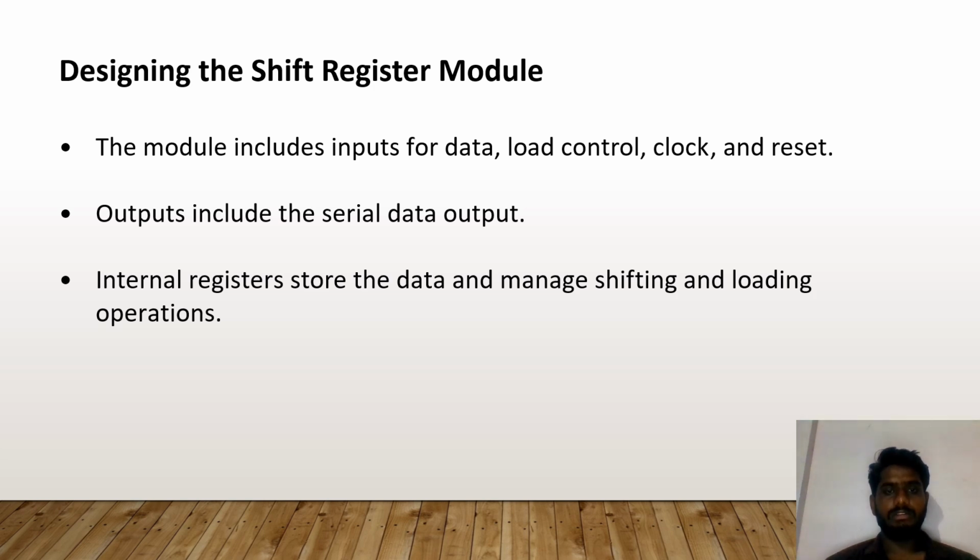Designing the shift register module. The module includes inputs for data, load control, clock, and reset. Outputs include the serial data output. Internal registers store the data and manage shifting and loading operations.